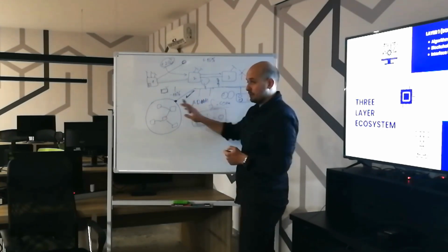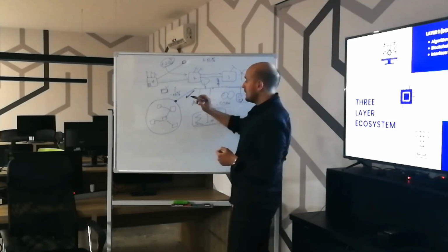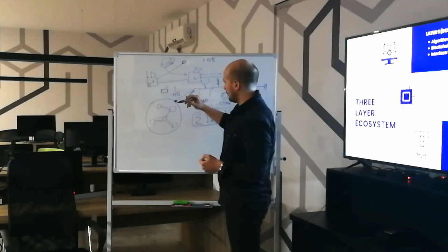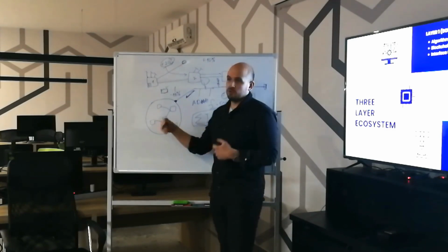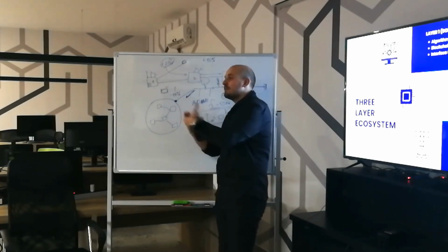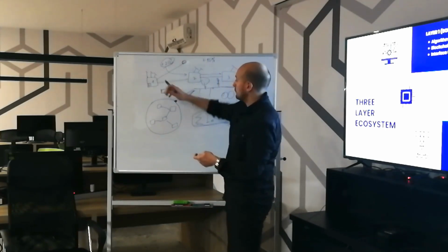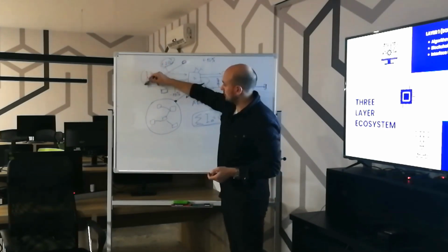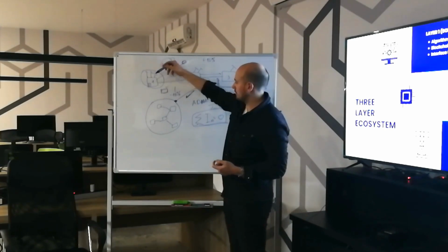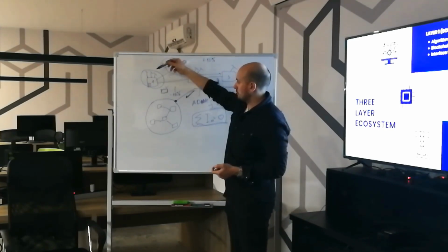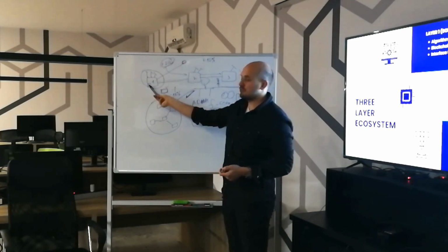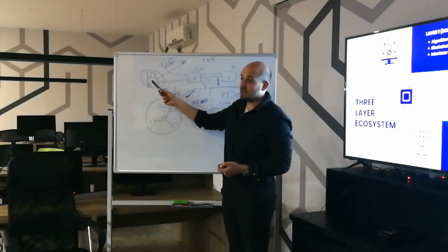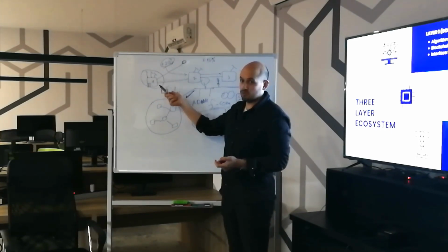And whenever we have a situation, for example, a regulatory limitation to export the excess of energy to the central grid, then we'll need storage batteries. So only in this case we need storage batteries. If we compare the first solution that we are addressing now, which is most common today, only one household which uses renewable energy resources needs storage batteries. So it can be self-sufficient in most periods of time.